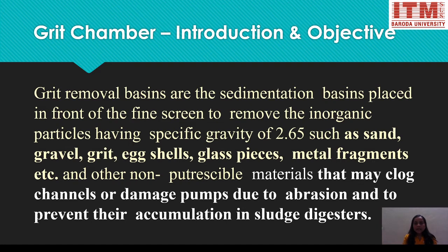Now the screening material which is retained will be removed and disposed, and whatever material and wastewater has passed through the bar screen will come to the grit chamber. Grit chamber is basically a settling tank.